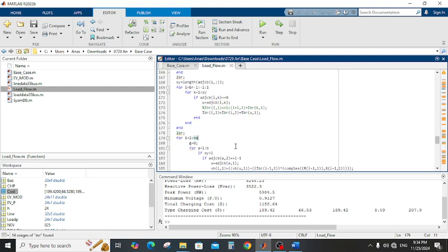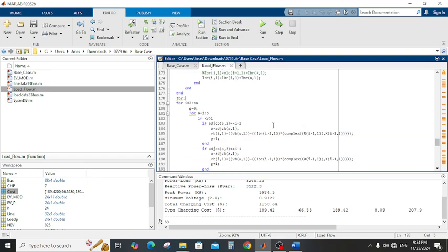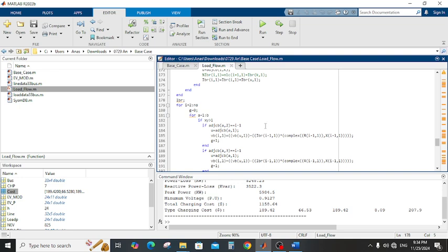After we calculate the accumulated branch current, we feed forward to calculate the bus voltages, as you see here. From the calculated branch current and from the resistance and reactance, we calculate the new voltage of each bus, depending on the first process of calculating the branch current.